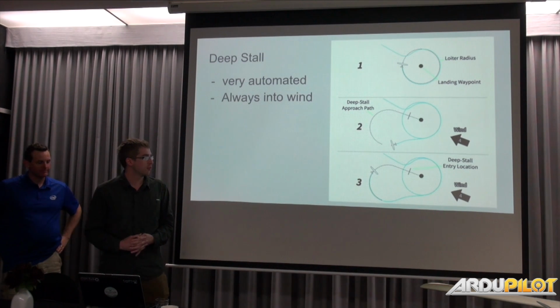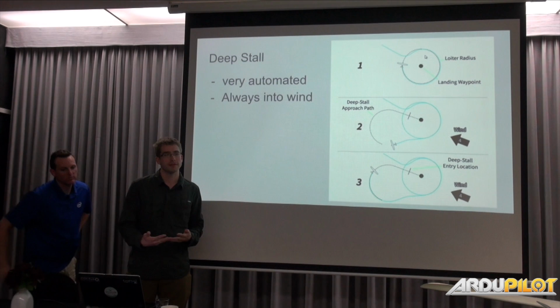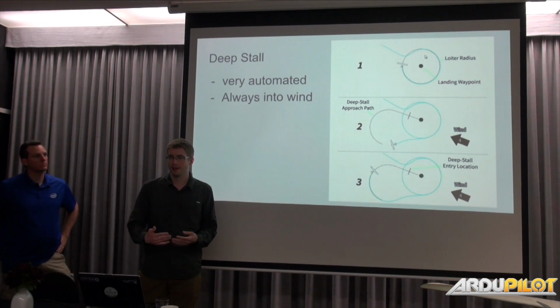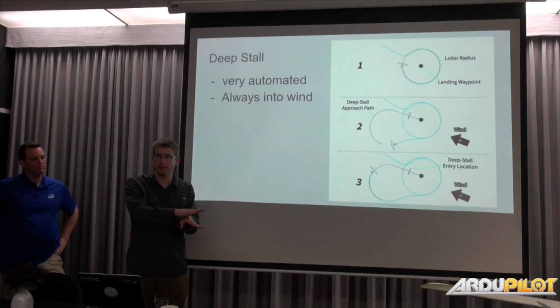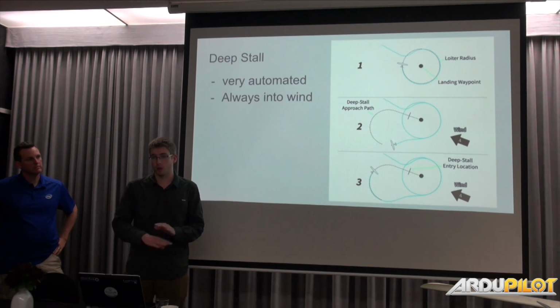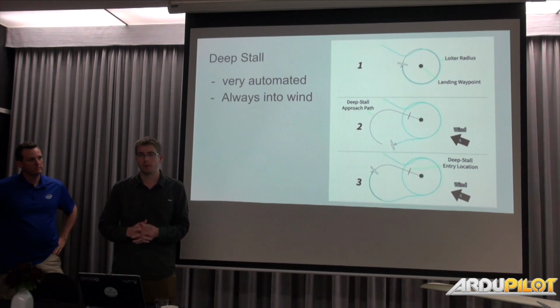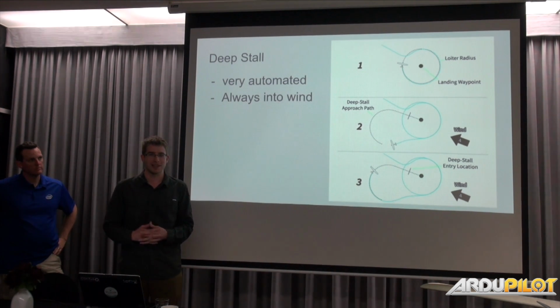So for deep stall, there's a couple of important parameters to tune. The main one is that this is using vastly more elevator control than the autopilot is allowed in flight. The autopilot for us is normally using maybe 10 degrees or so of elevator travel, and going into deep stall, we're pulling that up to about 40 degrees. So we're actually manually overriding and specifying a PWM value for now. It's only allowed during this mode because it's unstable and fast on the outside, but the autopilot can't fly it. We gave the autopilot that much control, and it just porpoises; the PIDs wouldn't handle it.